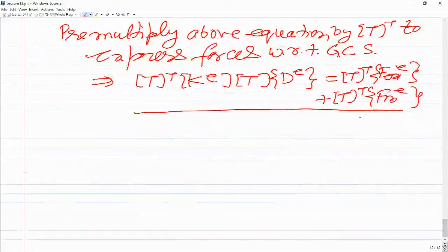And when you look at this, there can be a situation when all the elements are in the same plane. Then all the stiffnesses corresponding to theta z would be 0. So the assembled stiffness matrix, even after implementing the boundary condition, would still be singular. So you add a small value in the diagonal elements corresponding to theta z degrees of freedom, and then you solve the problem. So that is how the entire thing is done.